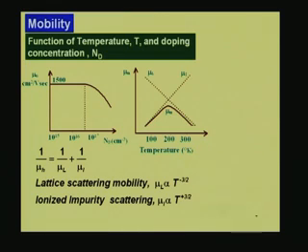affects the mobility once the doping concentration is somewhere around 5 times 10 to the power 16. Till that time, the mobility in silicon, because we are talking of silicon at the time being, is constant for the electrons, that is about 1500 centimeter square per volt second. But once you go to doping concentrations which are 10 to the power 17, 18, etc., which you may not like to do, because mobility will fall.